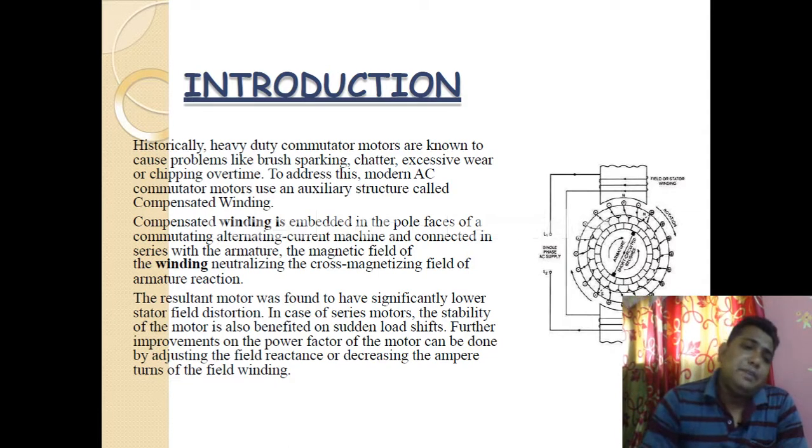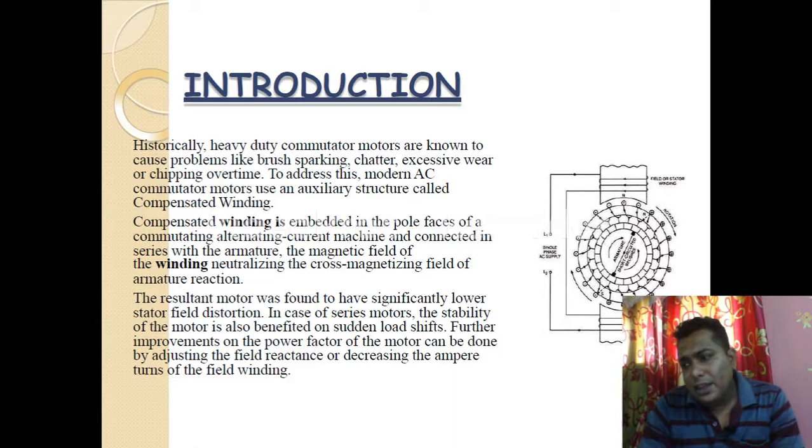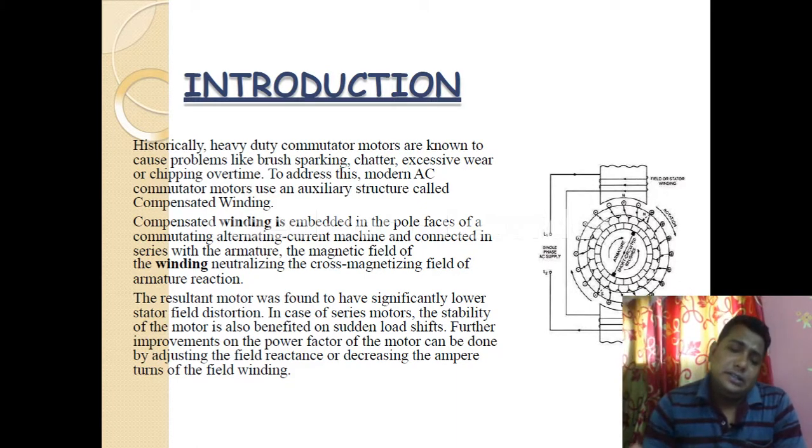The repulsion motor was found to have significantly lower stator field distortion. In the case of a series motor, the stability of the motor also benefits on sudden load shift. Further improvements in the power factor of the motor can be made by adjusting the field reactance or decreasing the ampere turns of the field winding. These are the main characteristics we have in the case of compensated series motors. So let us start.